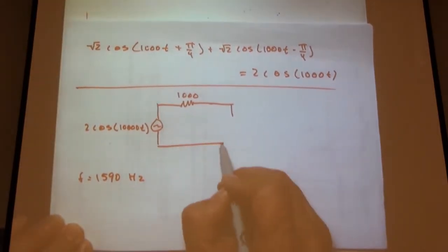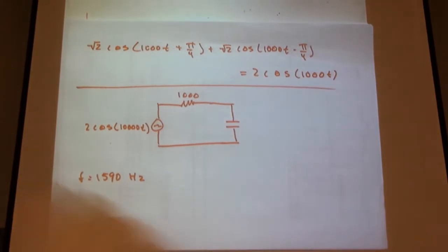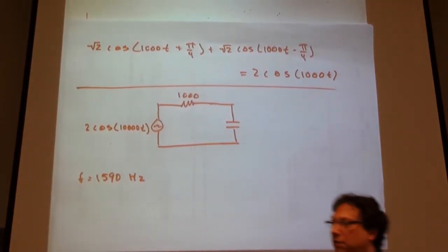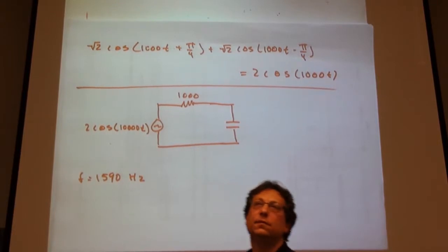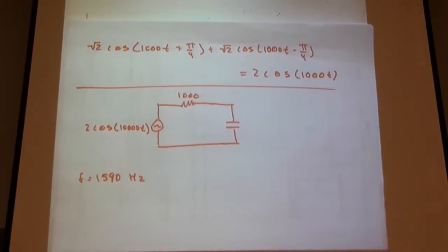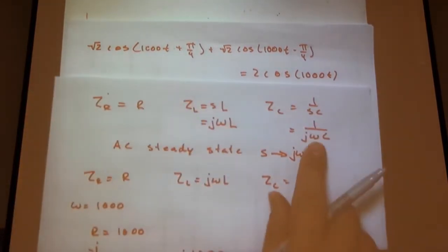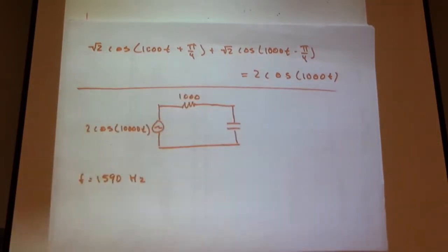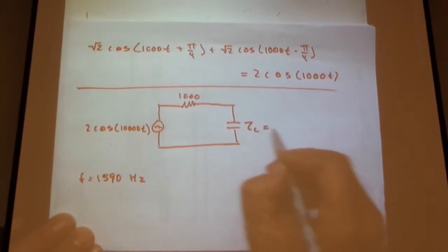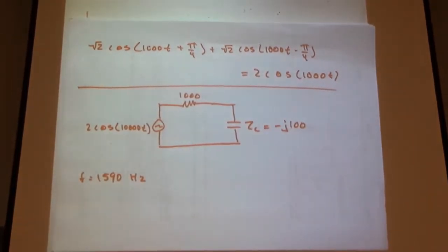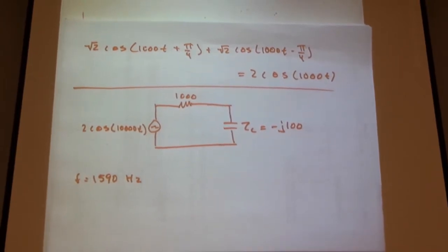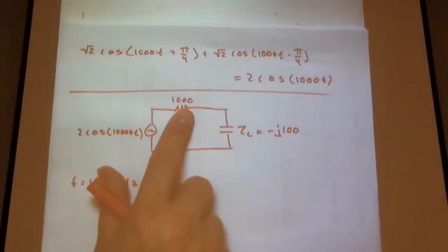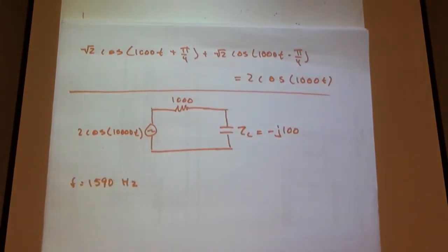And so, what's going to happen with our capacitor impedance? As frequency goes up, what does capacitor impedance do? It goes down. That comes out, again, of our relationships. As frequency increases, capacitor impedance reduces. So as ZC becomes smaller, what do we expect? We saw this again in the lab yesterday. It doesn't matter if this is an imaginary number and this is a real number. The concepts of relative magnitude still apply.